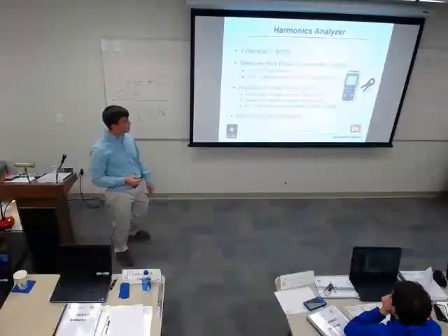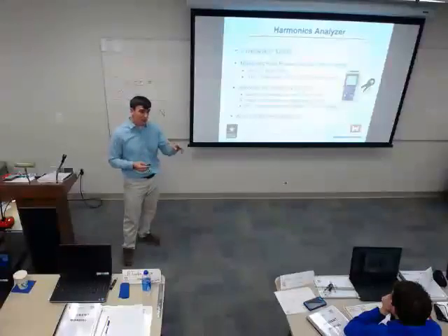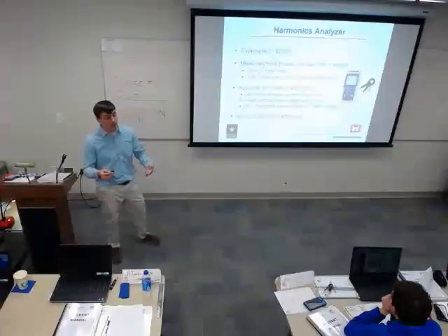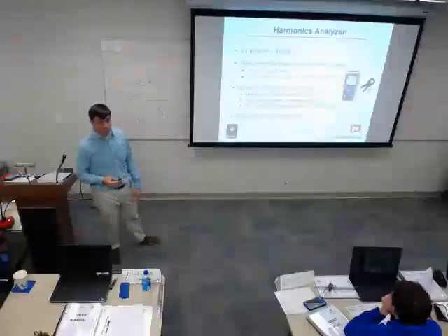But we're typically reading and reporting voltage and amperage. Big thing, we care about both of them, but we're really trying to make sure we're not exceeding that amperage on the motor rating.